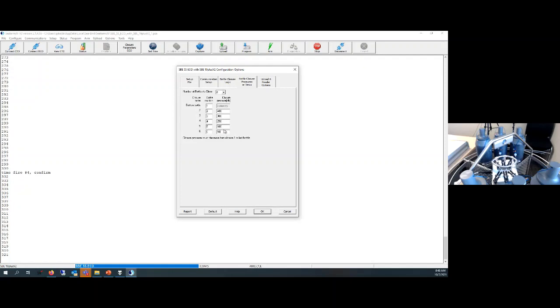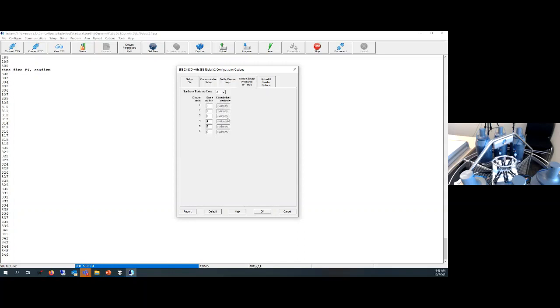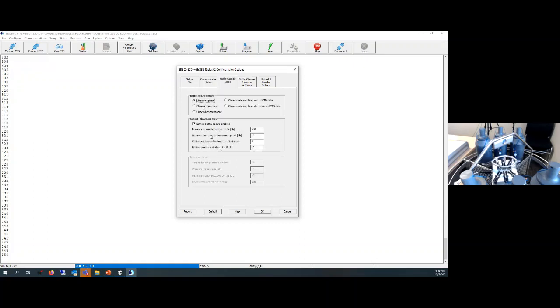In this case, I would recommend, if you can, monitoring the amount of wire out from your winch to estimate when you're reaching nearby these pressures, and then slowing down the CTD package as you're getting to these points. That is sort of the best case you can do with autonomous bottle firing. That being said, instead, you can also use the close when stationary logic. In that case, all of these are going to close when the system is held stationary, very similar to the pressure window and timing we set in the close on upcast option.